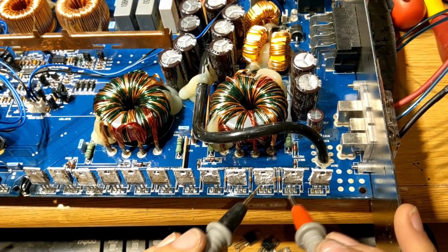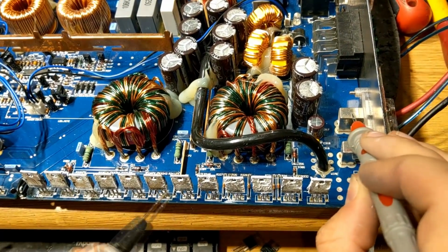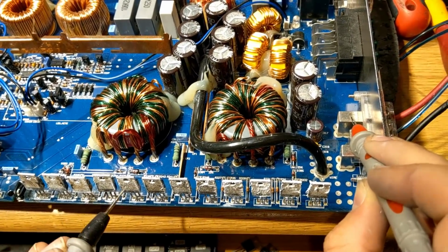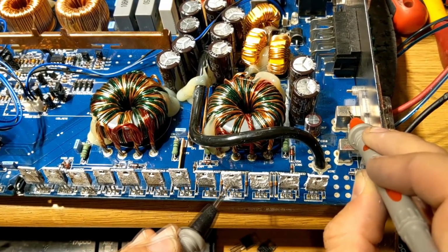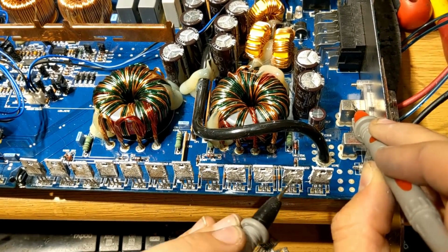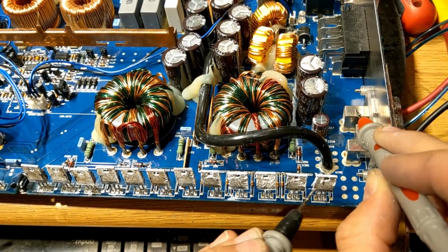So it's meant to be on the backs of these. Okay, so we have 12 volts coming in here, and we have 12 volts on this bank, 1 2 3, this bank, 1 2 3, this bank, 1 2 3, because it's beeping. But this one, we have nothing. So 12 volts isn't making its way to these 3 FETs, and that's why it blew.